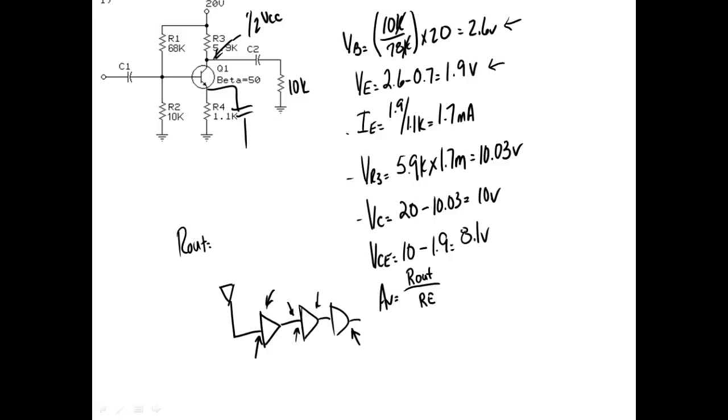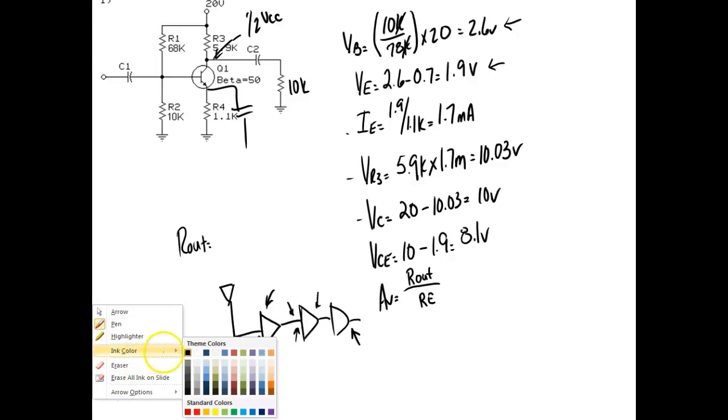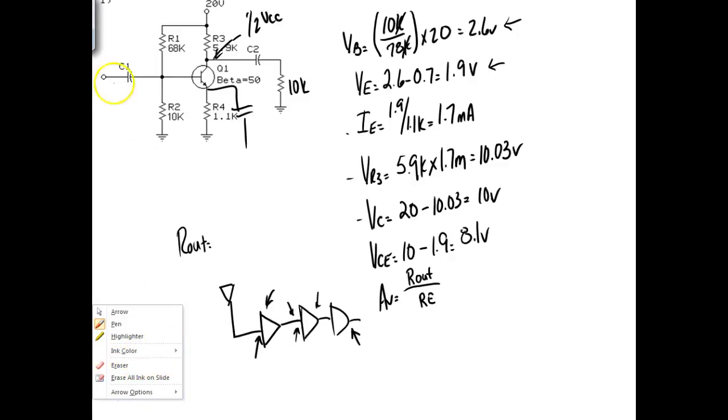That makes sense? If we don't bypass it, we increase the input impedance, which means whatever's driving this doesn't have to provide as much current, right? We still get a gain, but not gains of 80s and 100s. We can still get a gain of 4 or 5, right? If I get any gain at all, I can feed it into my next amplifier stage. Does that make sense?